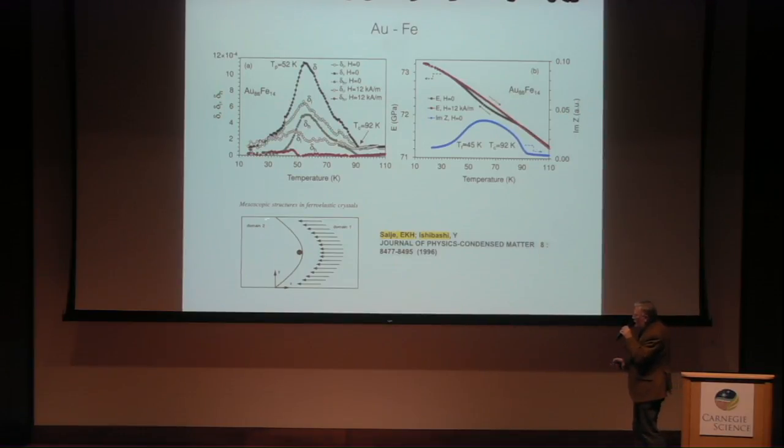And the idea is really what we call vaulting. I mean, vaulting means basically it's a nice word for wiggling. So if you have a few defects in there, you have a domain wall, you have a defect, then these domain walls locally, it's largely exaggerated here, will bend over, and that costs energy. And this energy is the dissipation which goes into the friction coefficient. I mean, we worked with Ishibashi on that in '96, so that's how it looks like. And of course, when your landscape is very smooth, then you don't have these point defects, and they can just wiggle over them, and you don't see any singularities.